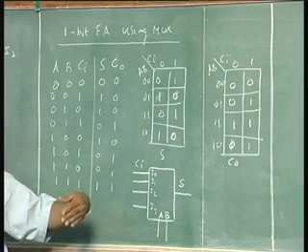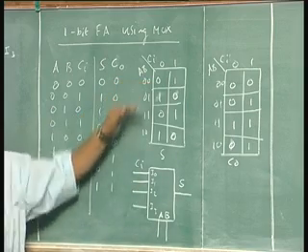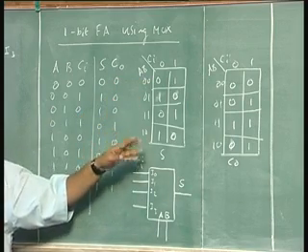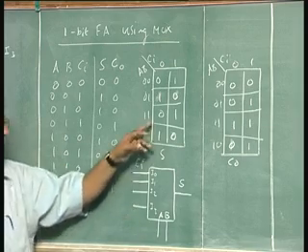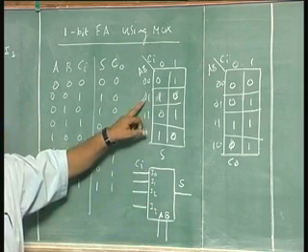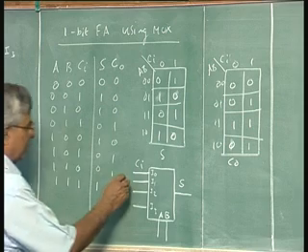But what is so intuitive about it? Because I chose this A and B as the selector variables and found out that this is how it has been done this way. I can also do it some other way. Now, when AB is 0, 1, output will be 1 when Ci is 0 and 0 when Ci is 1. So, I need to connect Ci bar.